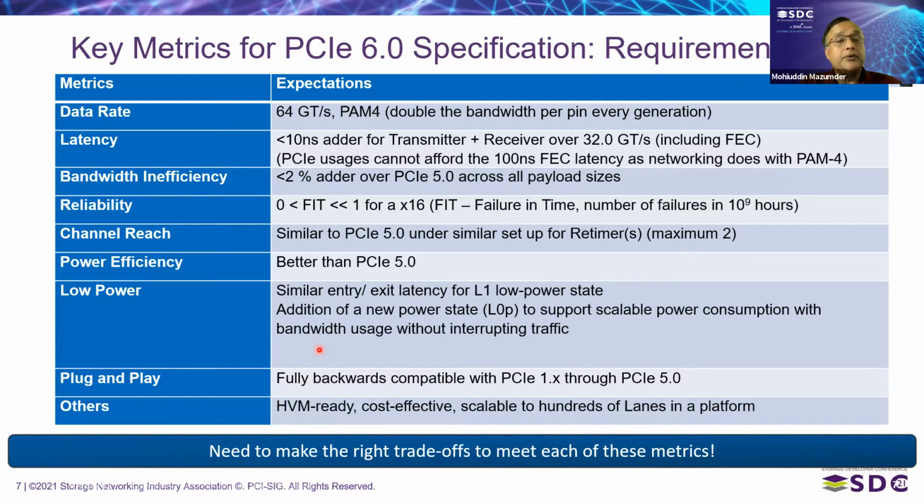This is not new technology, but this is needed, and what is new and what are the specific features in PCIe, we will discuss in the next few slides. The next biggest and hardest requirement was the latency. PCIe is a load store I/O architecture. It cannot tolerate large latency.